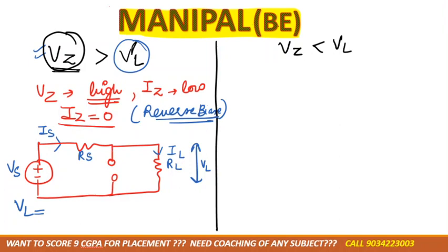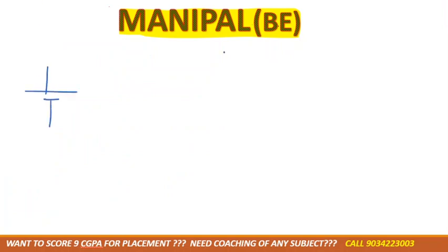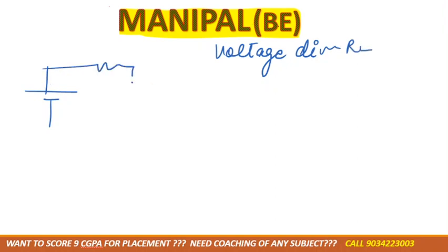Now as you can see, RS and RL are in a series circuit, and in a series circuit, to calculate the voltage, can we apply the voltage division rule that you have studied in BT? Did you know about the voltage division rule? So what is this voltage division rule? Whenever the circuit's resistances are in series, then we can apply it to calculate the voltage.